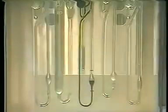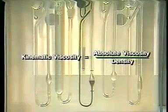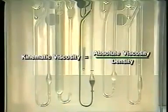To show the relationship between absolute viscosity and density, a measure called kinematic viscosity is used. It compares the liquid's absolute viscosity with its density. Kinematic viscosity is measured in a lab with a special instrument that measures flow in units of time. The measurement is taken in the lab and then converted to a unit called centistoke. One reason for finding kinematic viscosity is to determine how much the liquid changes with temperature. This is especially important with motor oils.